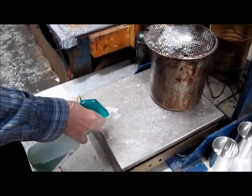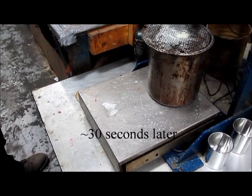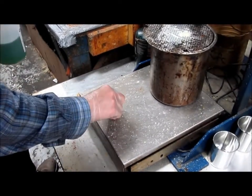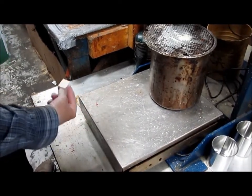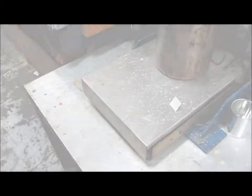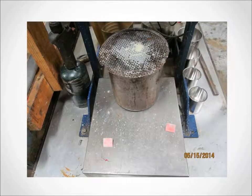To test, we first lightly spray the area with the aromatic amine cleaning developing solution. You wait about 30 seconds, and then an aromatic amine surface swipe was run across the surface, and the color was allowed to develop for about 5 minutes. After half a minute, the red color was already developing, as expected with a noticeable contamination such as this. Allowing the swipe pads to fully develop, a definitive MOCA presence is shown, with a deep red color on the swipe.